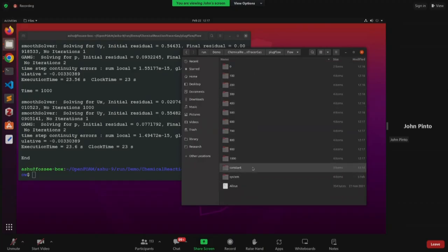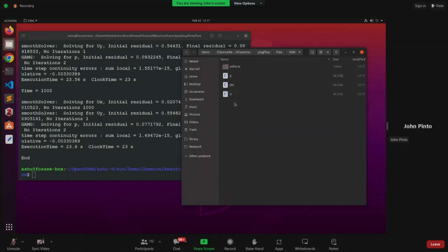flow, the new files have been written just now, 1217. Yes. So I will open the last iteration, the velocity from there. I will copy it. Okay. Control C, and I will paste it in my scalar simulation 0. So this is my new initial condition now. While I'm pasting, it will ask replace. I said, okay, replace it. So I have imposed a new velocity. So this is how you have to impose a new velocity.